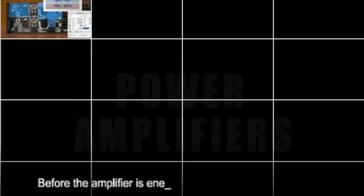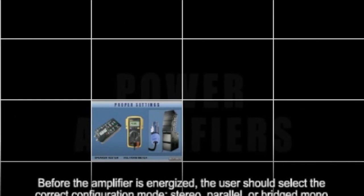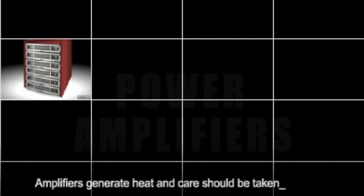Before the amplifier is energized, the user should select the correct configuration mode: stereo, parallel, or bridged mono, and check the loudspeaker lines for shorts. Amplifiers generate heat, and care should be taken to ensure proper ventilation around the amplifier. Amplifiers are dependent on their required AC power in order to produce the output they are designed to deliver.